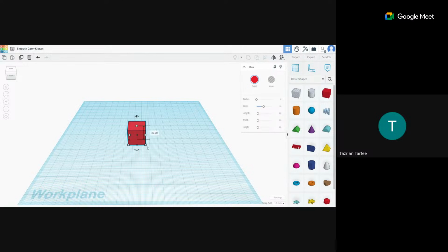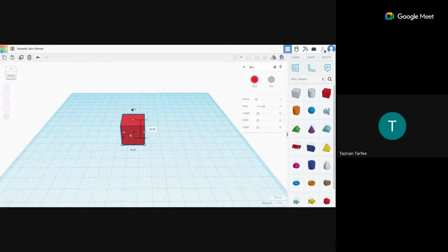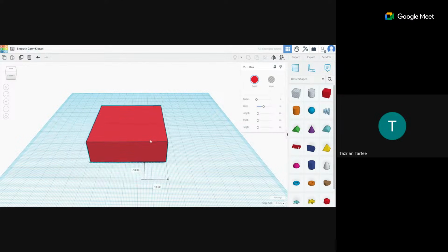So if you put the shape down, you can see there are 5 white squares and a couple black squares, and we're not going to worry about the black ones, but the white squares are for dimensions. These dimensions, if you click on any of the bottom squares, are going to be 60. So they're currently 20, and we want to change both of them to be 60.